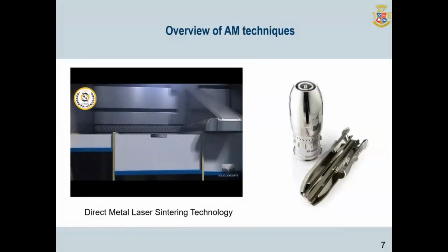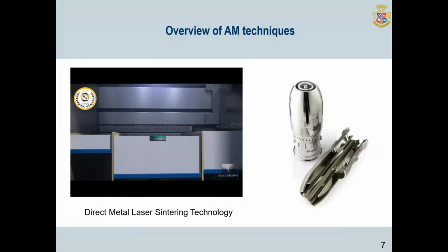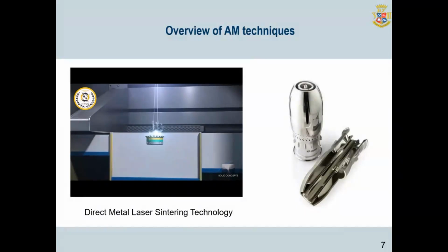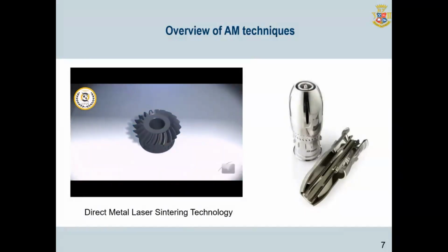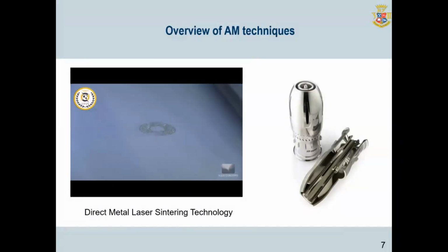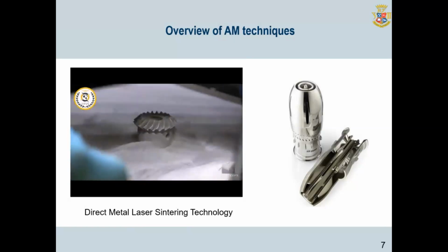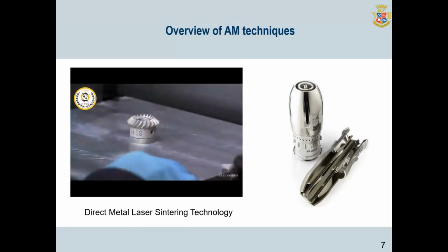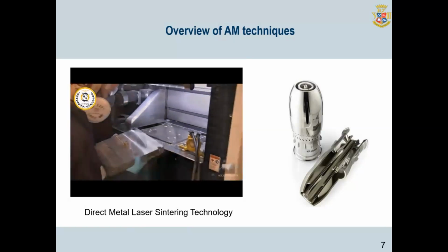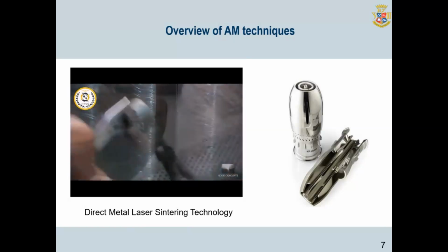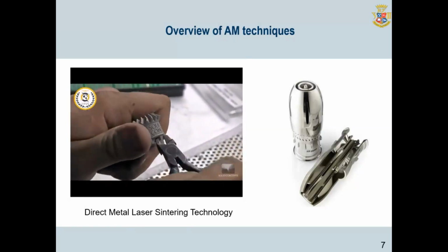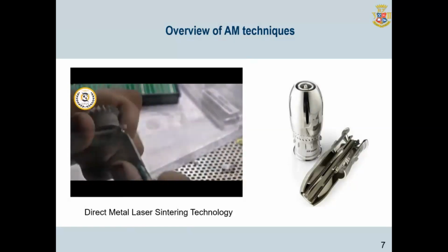Once a single layer is complete, the base plate is lowered just enough to make room for the next layer. More material is raised from the cartridge and recoated evenly upon the previously sintered layer. The DMLS machine continues to sinter layer upon layer, building from the bottom up. As the part is built, support structures are added to give supplemental strength to fine features and overhanging surfaces. The completed part is then removed from the base plate and treated with an age-hardening heat process to further harden the part. Any support structures are also removed at this time.